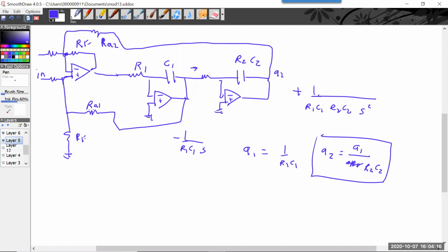Then I just have to worry, I'm not putting any gain. It's just, you know, the input isn't being scaled, so that's a gain of +1. And in this methodology, I'm not multiplying this by anything else. I just want it to be a +1 gain. So I have 2 here, right? I have another one coming on here. I need to balance it. And there's my RD. And I can set all of these equal to 100K, right? And that's C1 and C2, I can make a microfarad or a nanofarad. And then R1s and R2s will be the things that I'm going to change.